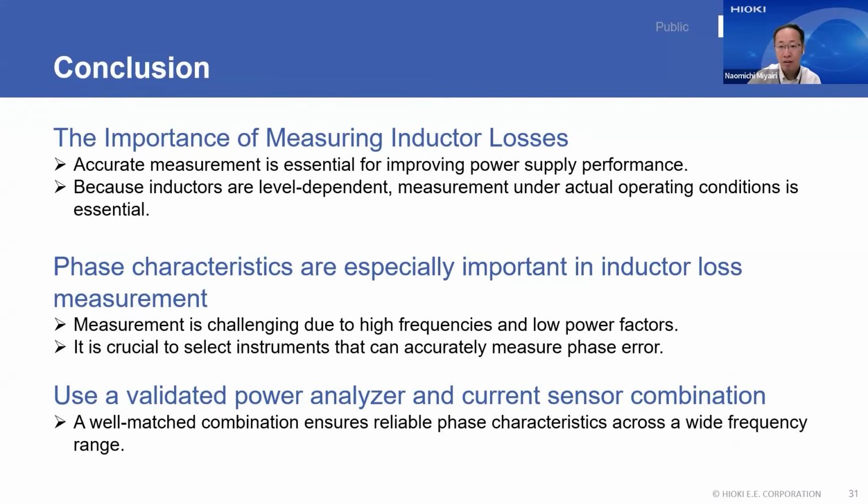Since the power involved is at high frequency and low power factor, selecting a power analyzer and current sensor with small phase errors and using them as a validated combination is key to obtaining reliable results. So we hope these 8 key points we covered today will serve as a practical guide when you set up your own inductor loss measurements.